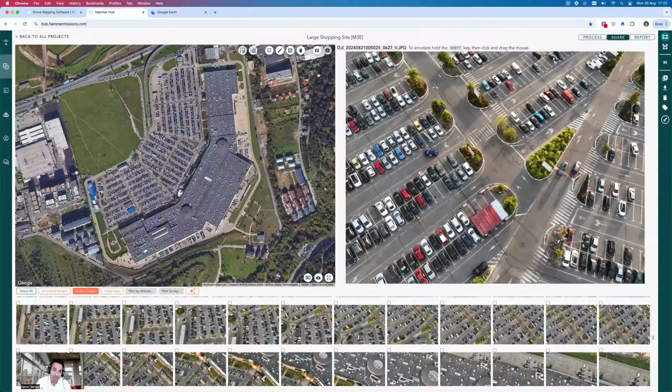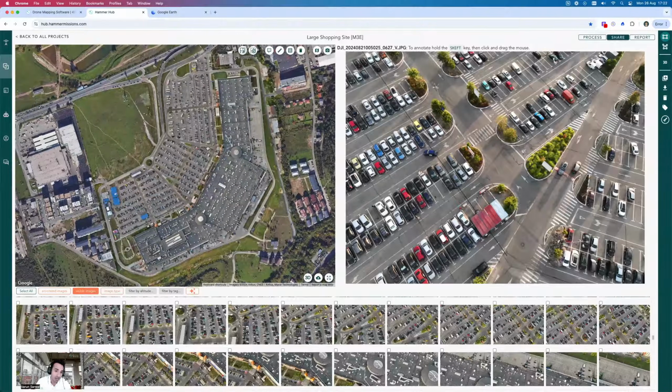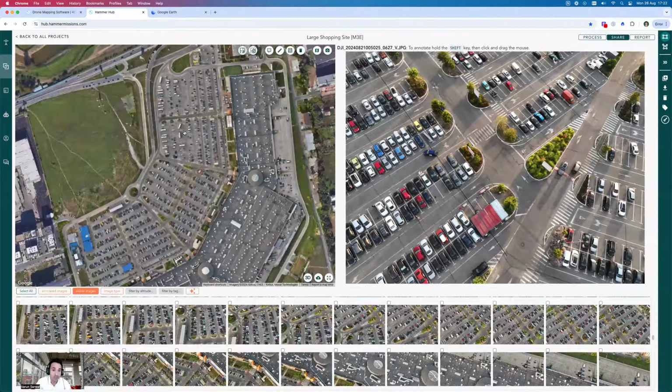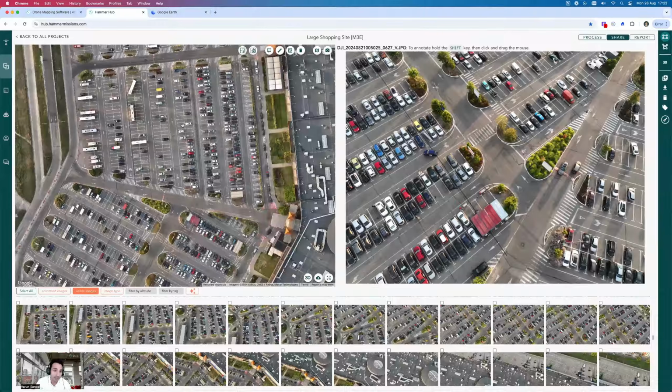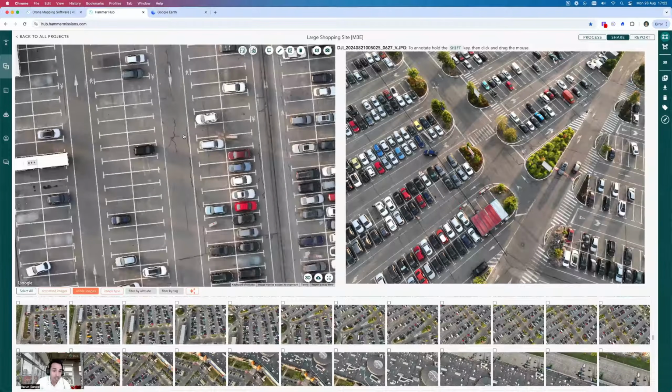And when you're planning works, sometimes what you need to do is understand how big structures are. So let's say you wanted to understand the repair for certain parts of this pavement. If you wanted to measure, let's say, the length of a crack, you can essentially do that. You can just click on this tool over here, and you can choose to understand the length of a particular crack. So you've got 4 meters of a crack over here, and you can measure that.